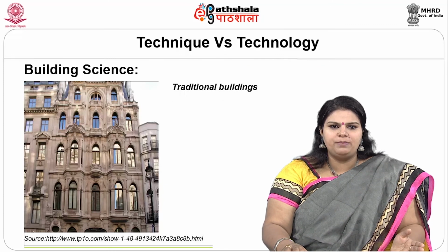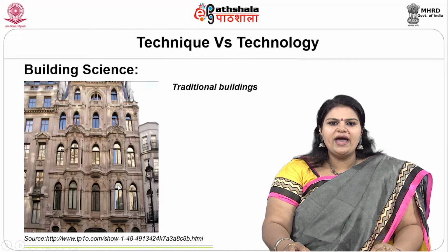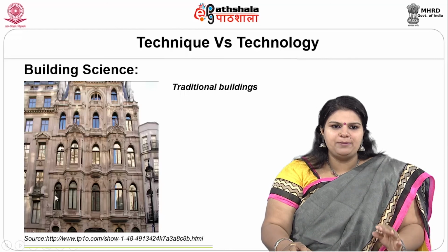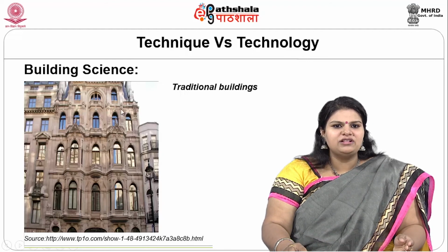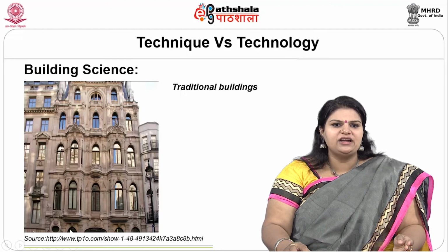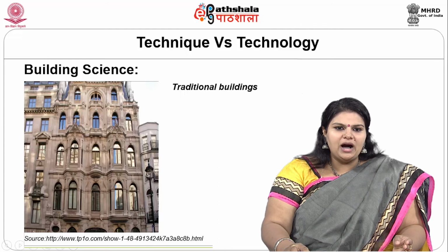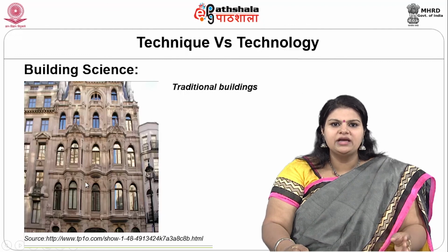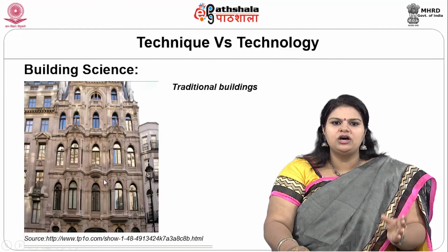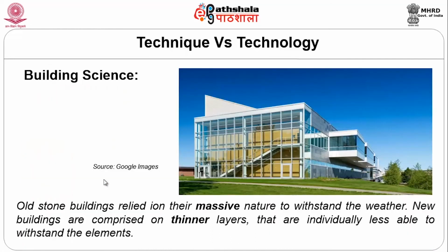We have a traditional building over here, building sciences, where the windows and glass are still very pertinent because that is the way daylight gets in. And every level that you see in this cathedral or any kind of towering structure, the mass of the building and the size, the percentage of fenestration to the building was in coherence to the climate that was there. Currently, if you see, we have huger and larger openings of glass. So besides permitting a lot of daylight, it does bring in a lot of sunlight as well.